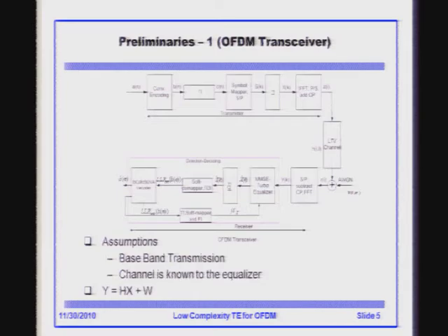After a few iterations, once you get sufficient convergence, the LLRs coming out of the BCJR decoder are hard sliced, and you get the information bits. So this is the general flow of information between the transmitter and receiver through the channel.